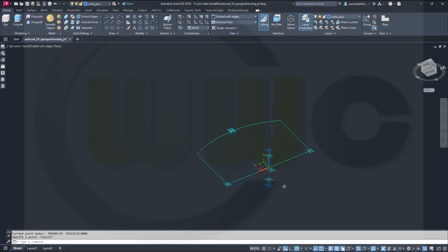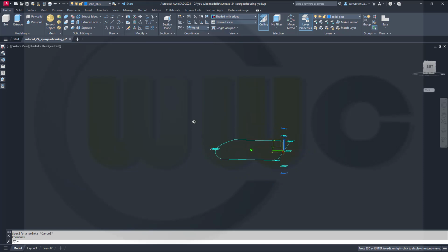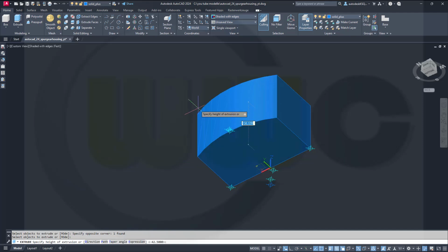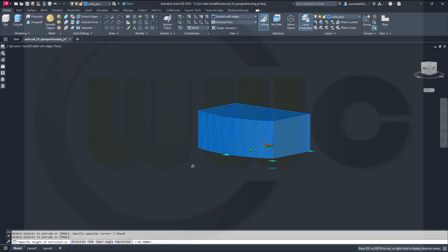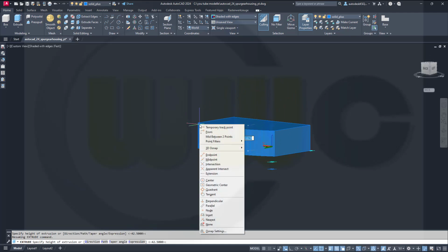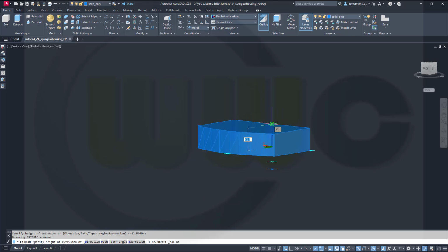That's just a lucky accident, because I'm right now on a different layer, so I can really see those 2 points. That's great. Let's go for another extrude with that polyline here. Right click, enter, and now it should go up to one of those dark blue ones. Right click and control node, that node here.